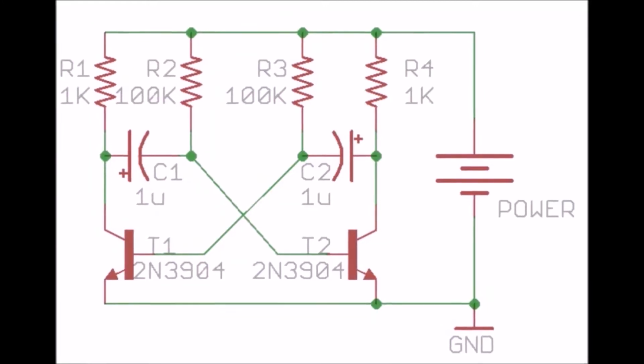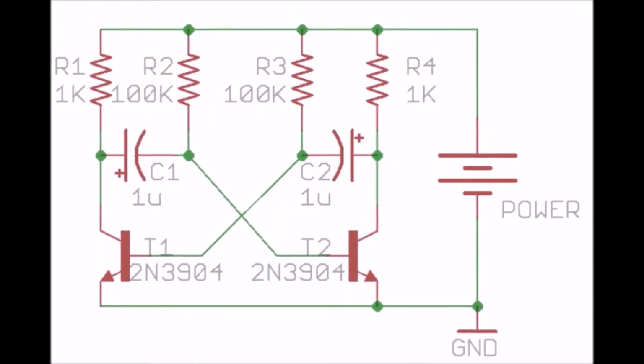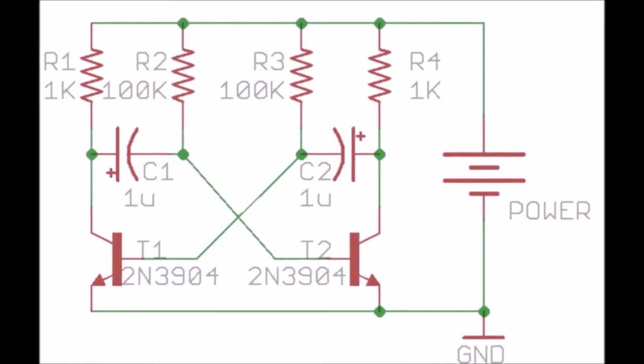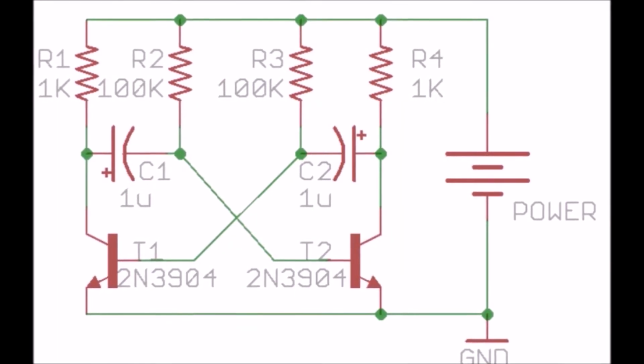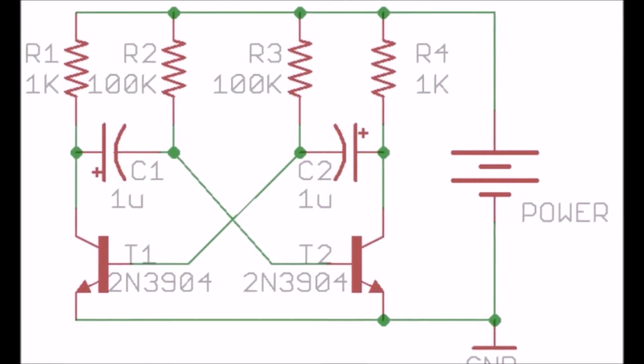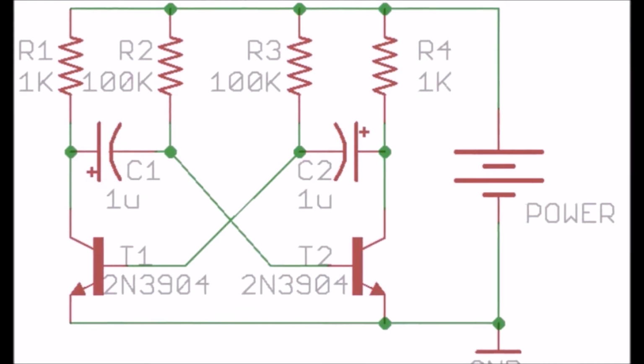This is the most common oscillator diagram. The first thing you'll notice is that it is somewhat symmetrical. Does that mean that the left half and the right half are both doing the same thing? Yes, but not at the same time. In fact, one half turns the LED on, and the other half turns it off.